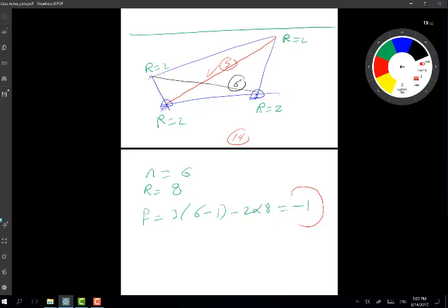So if we manufactured link number 5 with some error in the length, we could still fit it in the linkage, because the linkage was still moving, and we can still manipulate the distance between this point here, A, and point C, for example, till the distance between the 2 points matches whatever length we manufactured for link number 5, right? So this was quite possible. But once we fit link number 5 in the linkage, now we have a structure, and it doesn't move any more.